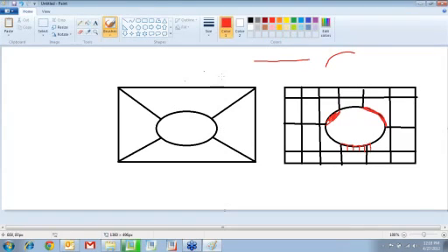Okay? In P-type FEA, the element edges order could go from 1 to 9. Okay, so it could be a 9th order polynomial curve which can match pretty much most of your geometric boundaries of parts, right?